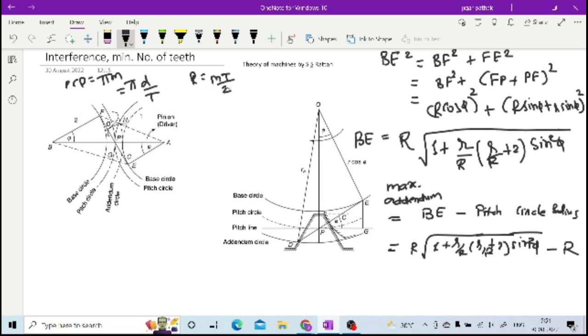So here capital R and capital T refer to the gear, right? Similarly for the pinion, it is small r and small t, right? This capital T and small t refer to the number of teeth on gear and pinion respectively, right? So this is how you have your capital R, small r and gear ratio G equal to capital T by small t.